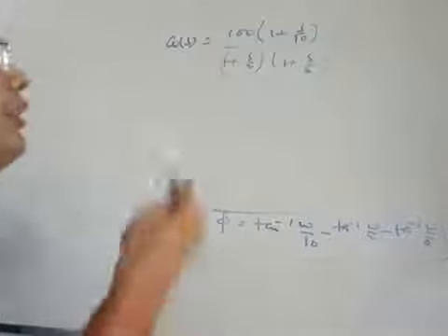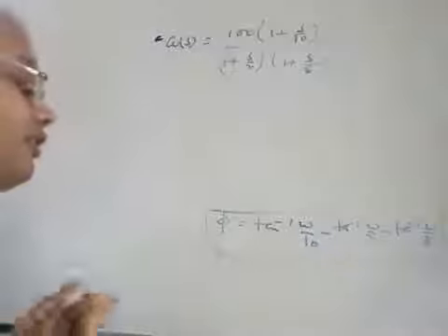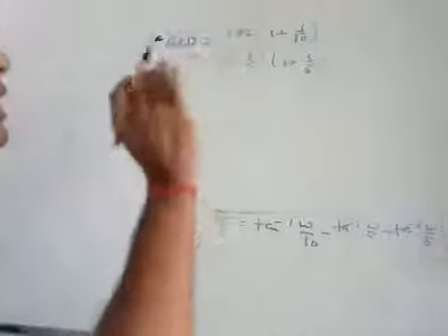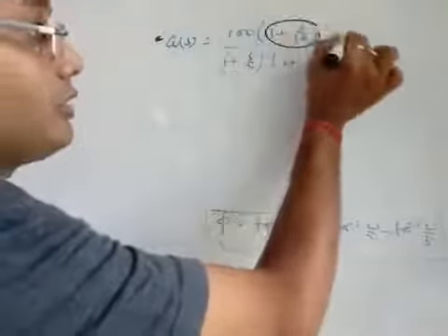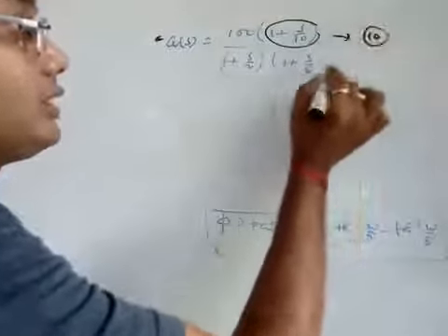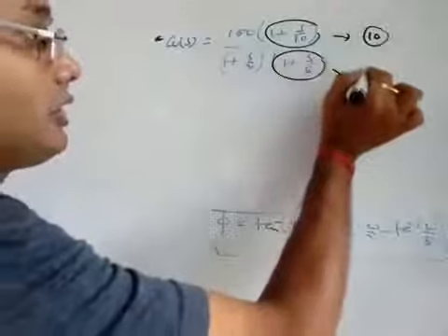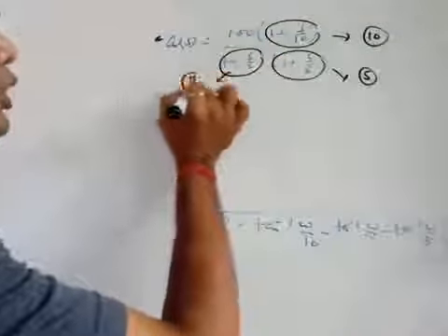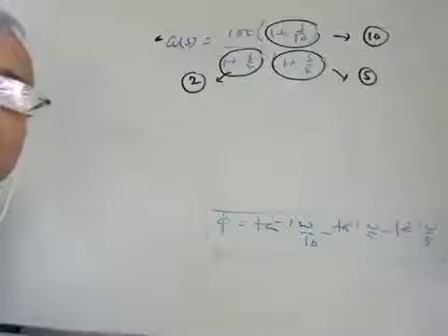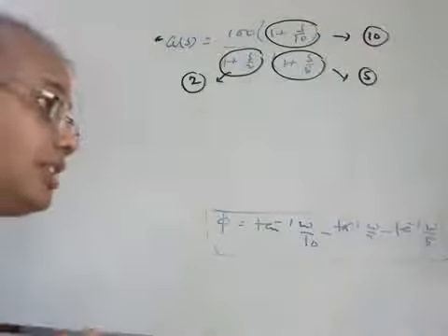Here we have written the transfer function in the time constant form. And what are the different corner frequencies we get from these factors? What is the corner frequency? You can tell it, the corner frequency is 10. What is the corner frequency for this? This is 5. And what is the corner frequency corresponding to this? 2. So we get three corner frequencies, right? Why are these corner frequencies required?